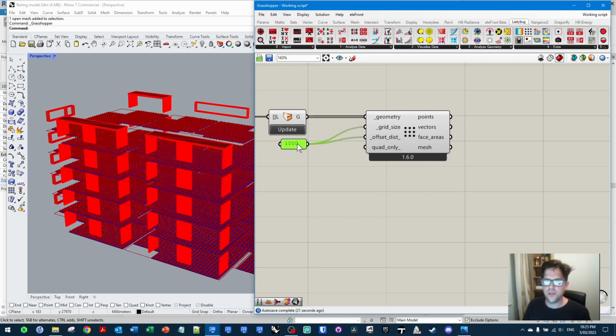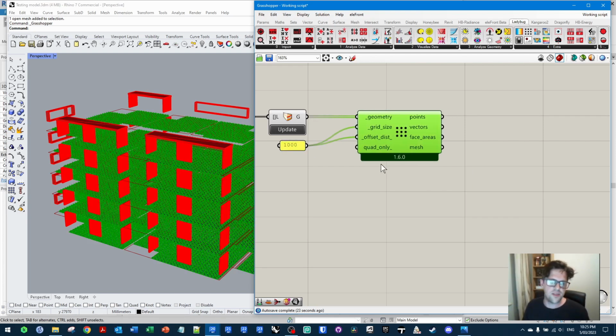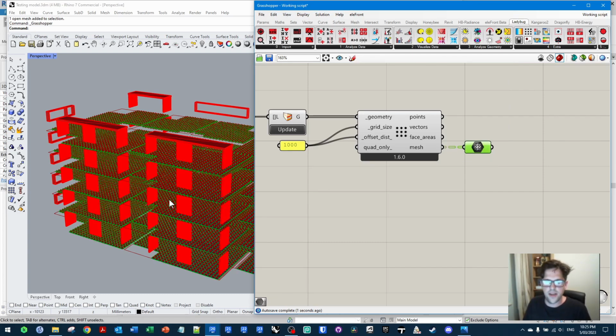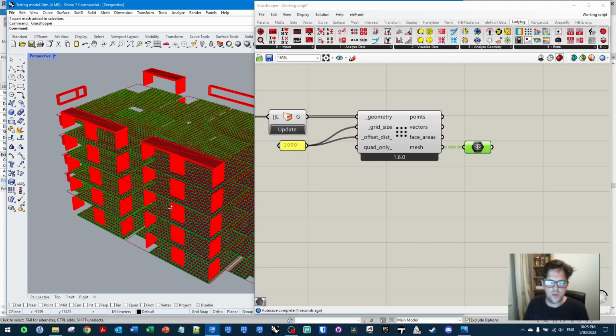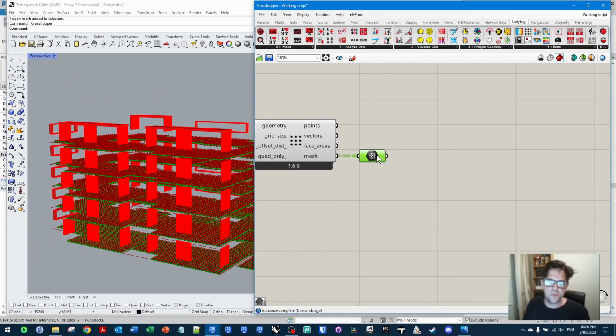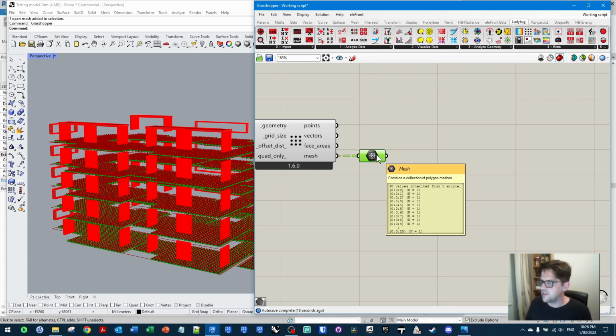Strange. I will use 1000 for my offset because generally when we are testing these surfaces in Ladybug, we typically need to test at a meter above the floor plane. But for now, it looks like our analysis mesh is going to be sitting down at the floor level, so we will have to be careful with how this goes further ahead. We could always offset this mesh up by a meter if we wanted to be safe, or we could use a meter later on in Ladybug and just test if it makes a difference if we make it 0. So I might just do that instead.